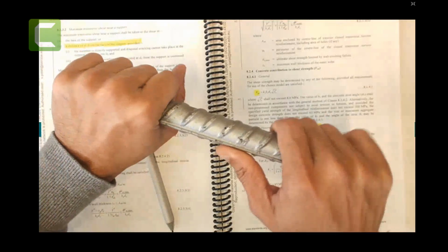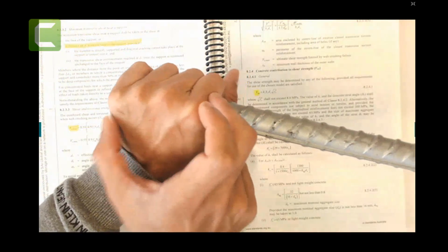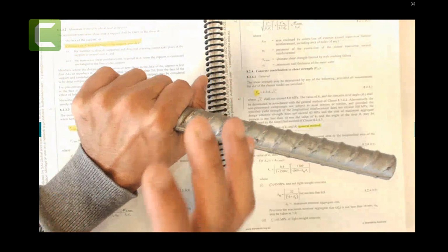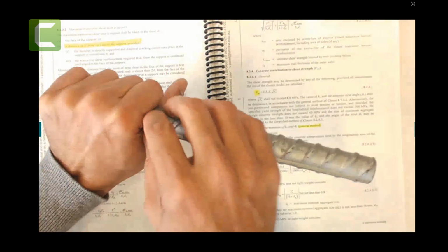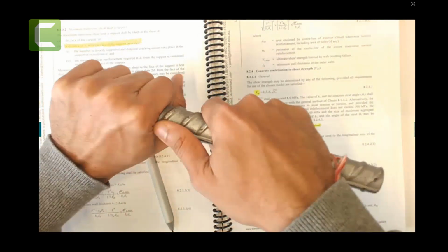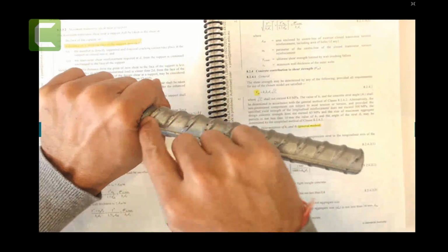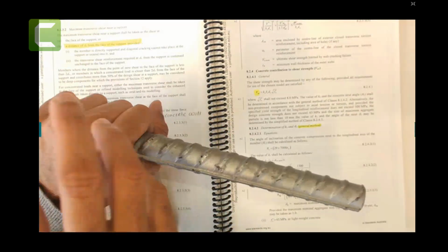So that is called development length. The length from this point to this point is the development length. That is the length that will hold the steel in the concrete when it cracks, and that will create the yielding at the particular point where it happens. So we need to design it. We need to provide the development length in a way that gives enough grip, in a general sense. I hope it makes sense.